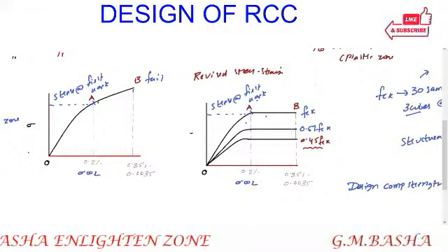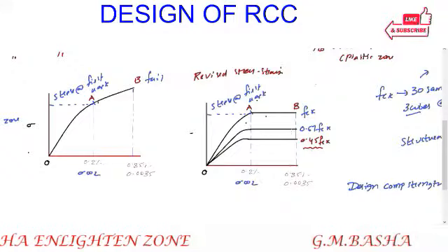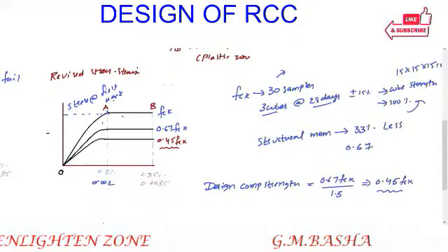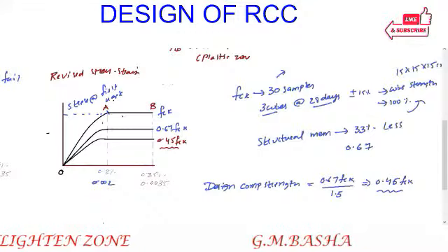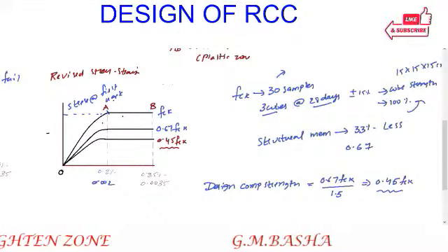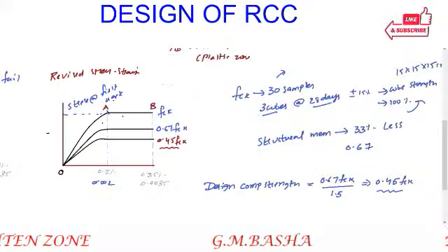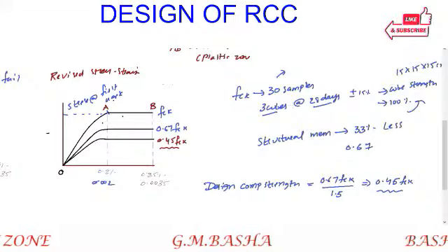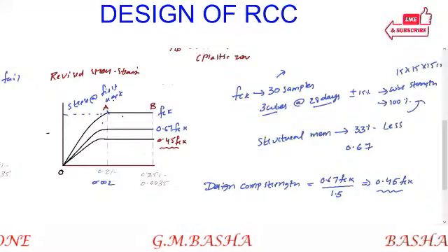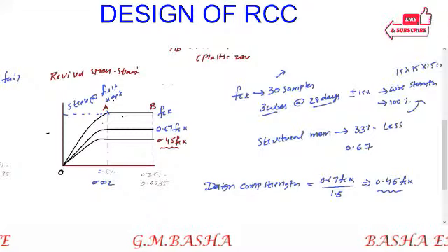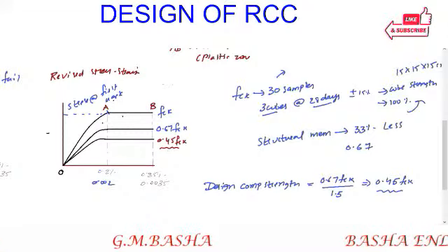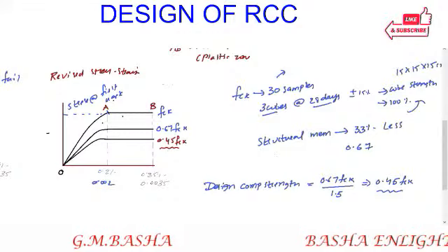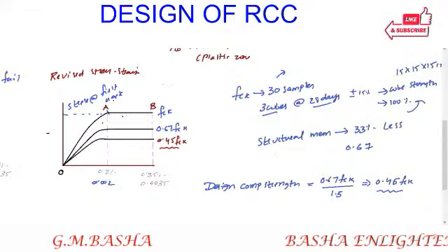For the characteristic compressive strength of the concrete, we have to consider a minimum of 30 samples, but it is not possible all the time. Therefore we consider 3 cubes at an average of 28 days with a variation of plus or minus 15% for obtaining the cube strength. The strength of any structural member will be 33% lesser than the cube strength.